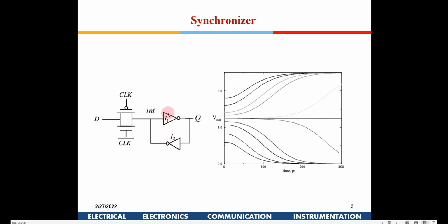Like if you have a VDD of 1, and it is exactly 0.5, then there is a small theoretical probability that it can remain stable at 0.5, this horizontal line, but practically that wouldn't happen because there will always be some noise. So this curve will get slightly pushed up or down, and then it will reach one of the stable states. So that is where VM is.